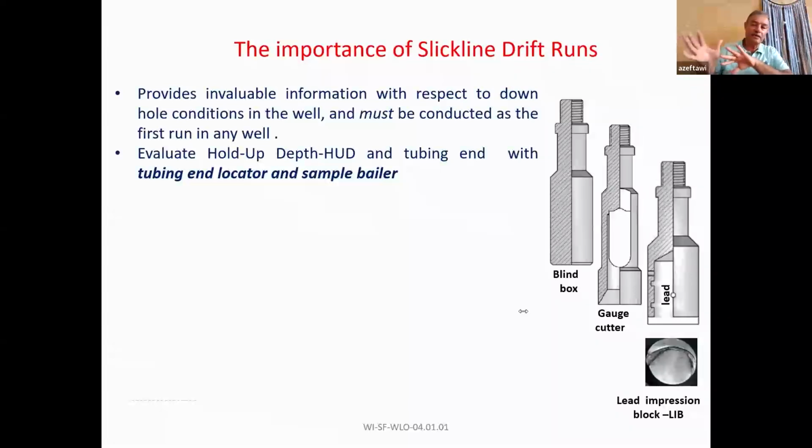So in wireline, whatever it is, slickline, braided line, E-line, yes, we can use a lubricator. But when we come to coil tubing, we cannot use any threads. So a lubricator is forbidden. We have to use a riser.